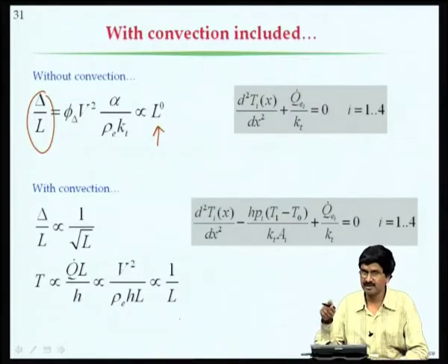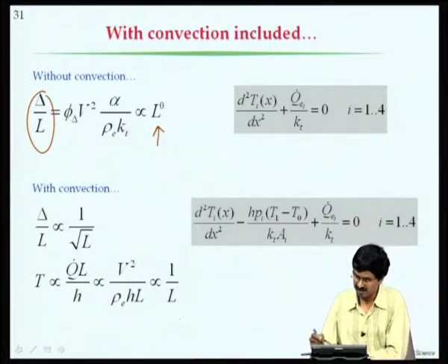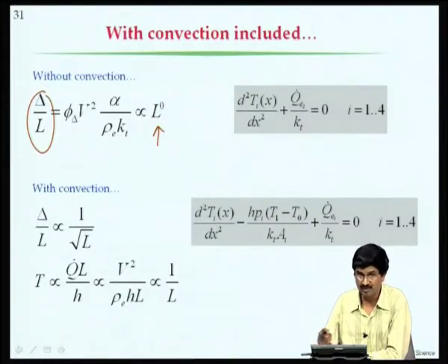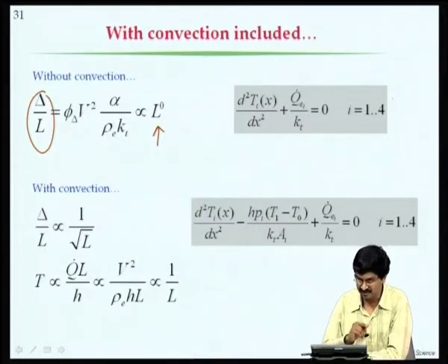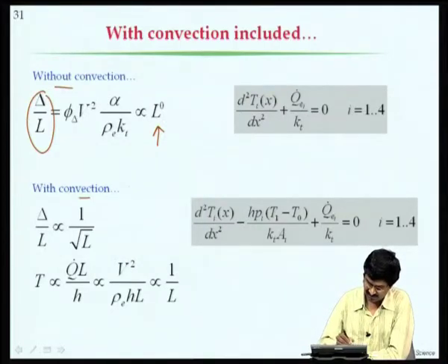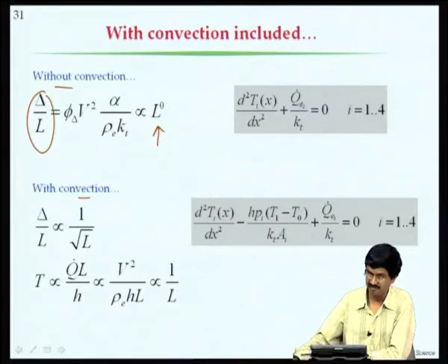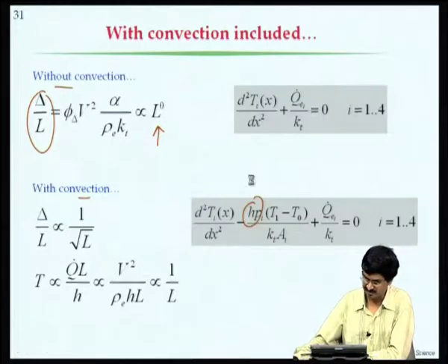If you have the appropriate properties for these two, a material can be used for thermal actuation. So, again we have the equations 1 to 4, and then we had neglected the segment 2 and took the heat balance anyway. Without convection, with convection we get a slightly different type of expression, and H here is the heat transfer coefficient.